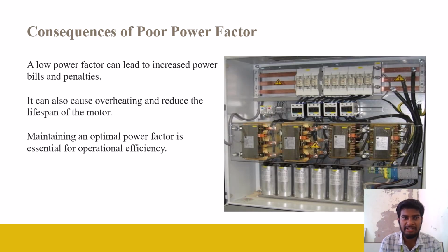And coming to the consequences of poor power factor. So what will happen if there is no improvement in power factor? A low power factor can lead to increased power bills and penalties. It can lead to increased power consumption, and it can also cause overheating and reduce the lifespan of the motor.